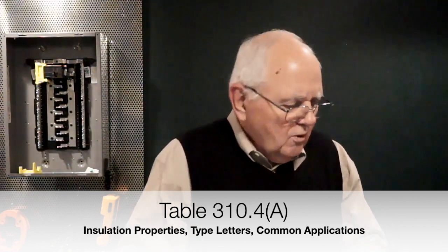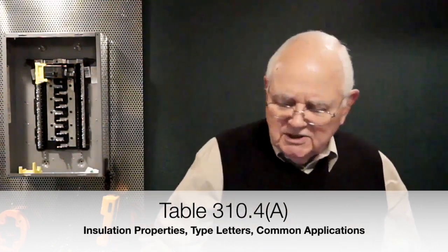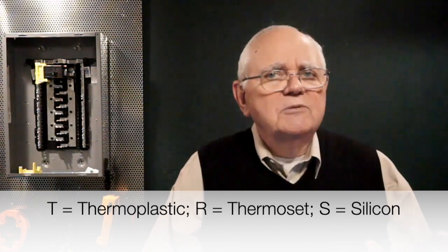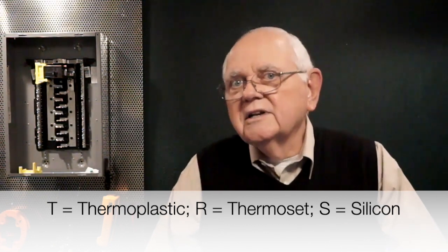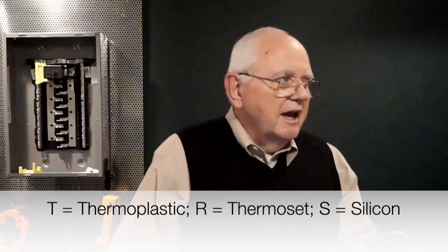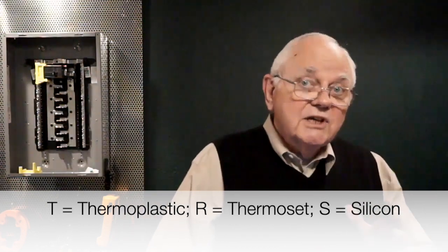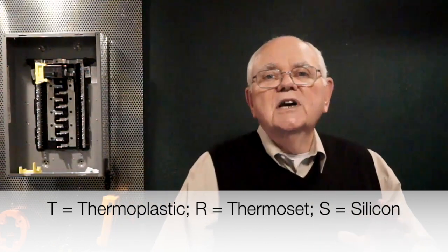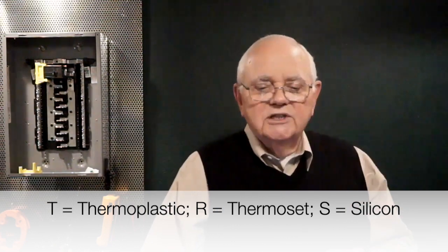Probably one of the most important then is our thermoplastic type insulation, as we mentioned, like our THHN or THHW. So let's go through some of those designations and see what we can figure out. T. So the T indicates that it's a thermoplastic type insulation. We said an R would indicate a thermoset. An S would indicate a silicon type of insulation. Some of the thermosets and the silicons have some very good applications at higher temperatures. And so the T indicates